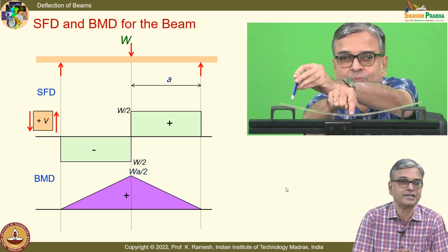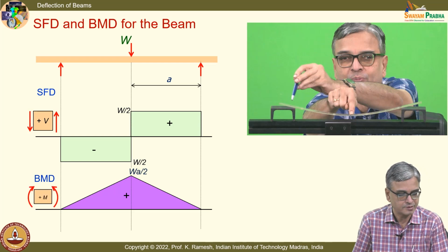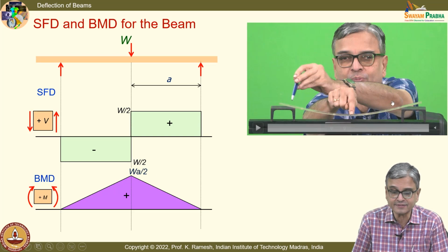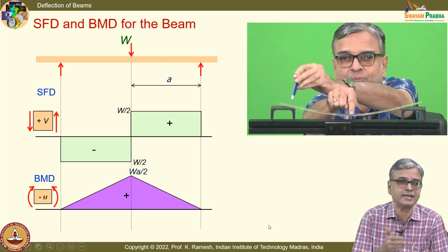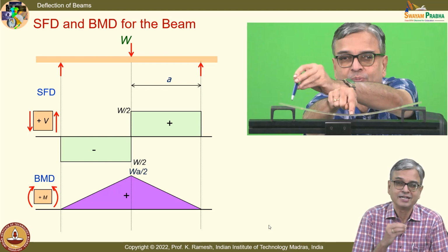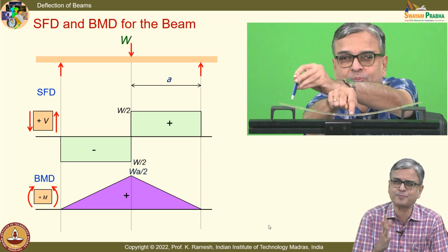We have the moment curvature relation. We should write what is the bending moment at a section, apply the boundary condition and get the two integral constants. And I have also shown the sign convention that we have been using in this course. So, everything is complete about this problem. So, you have to visualize. The idea is, in certain simple problems, I will give you the picture here. So, that should give you a training. When loads are given, you should be able to conjecture what could be the deformed shape. Looking at the support, looking at how the beam is loaded, you should be able to sketch it at least approximately.